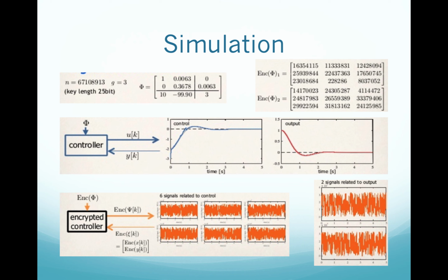So now we can move into a simulation that the authors went through, and you can see in the second figure where they did a simulation result for the time responses on the output Y, and then on the control input U. You can see here that there were some quantization errors in the control input response, and the output that was being monitored inside the control device.